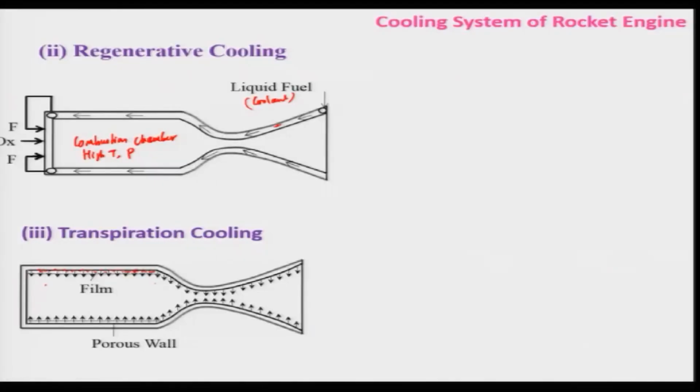In a similar way here, this is your coolant film which will be created on both sides, this line if you look at, and that will act as an insulating layer, and also it will evaporate, so that the temperature will be lowered. Unfortunately, porous materials which can withstand high temperature and pressure gases are not really being produced, and that is why it is not being used.